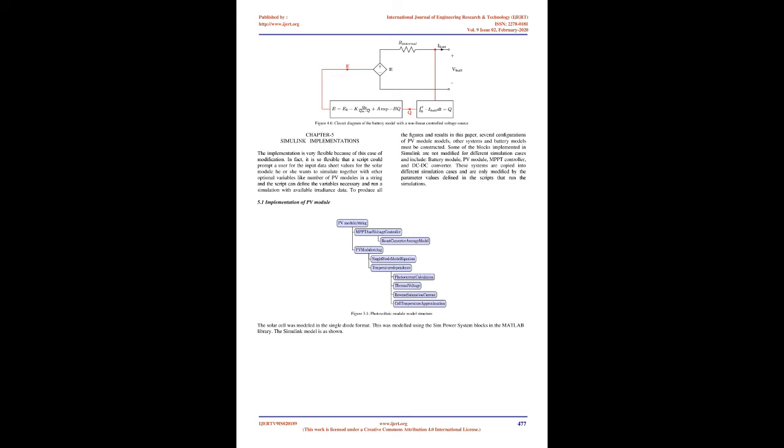If generated solar energy is integrated into the conventional grid, it can supply the demand from morning to afternoon, a total of 6 hours, mainly on sunny days. That is the particular time range when the SPV system can feed the grid. As no battery backup is there, the utility will continue to supply for the rest of the time period.